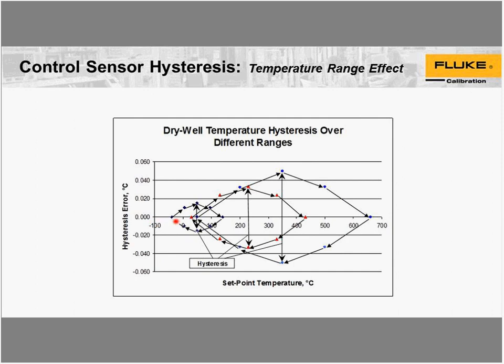We're looking at a number of different temperature spans for that temperature sensor, and you can see that the deviation in the center varies, but increases with the span. Now these particular deviations are somewhat exaggerated. At the small span here, you probably wouldn't see anything, at least not with the sensors I've tested in our dry wells.